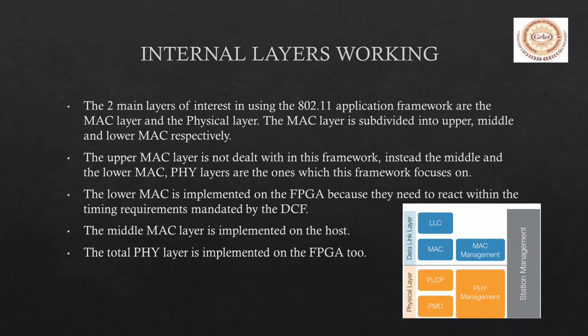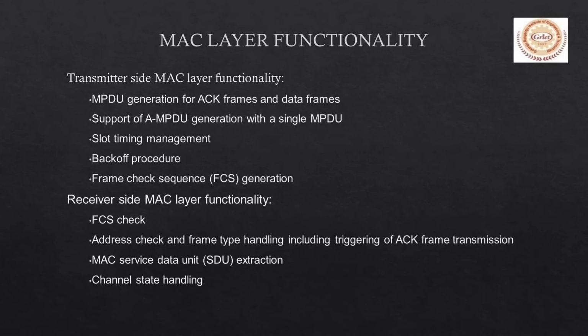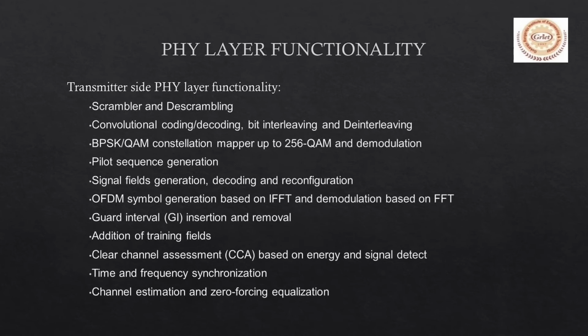Internal layers. The MAC layer is divided into upper, middle and lower MACs respectively. The lower MAC and PHY layer are implemented on the FPGA while the middle MAC is implemented on the host. We can see the MAC layer functionalities and the PHY layer functionalities shown here.